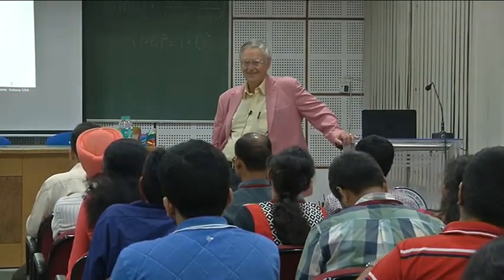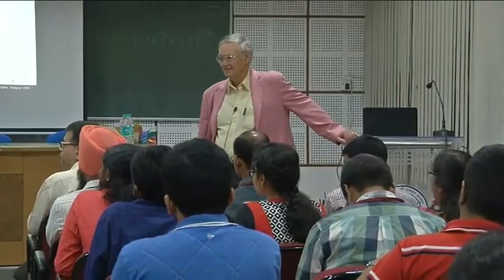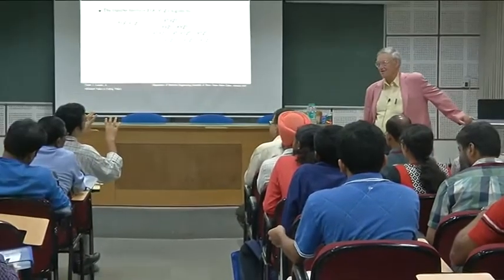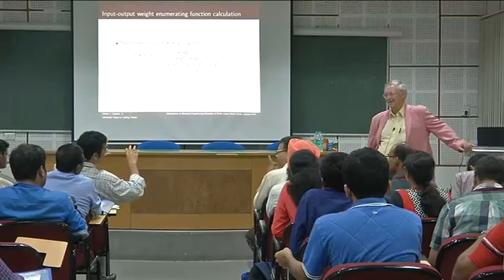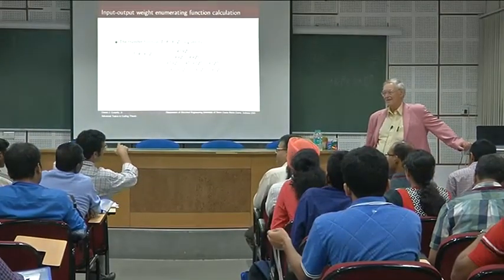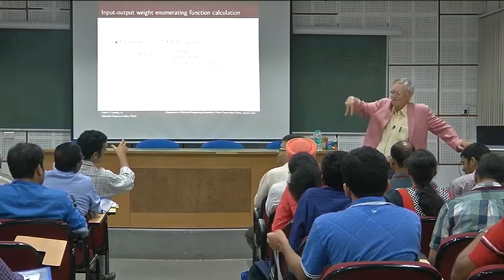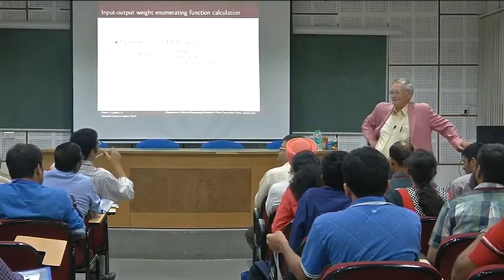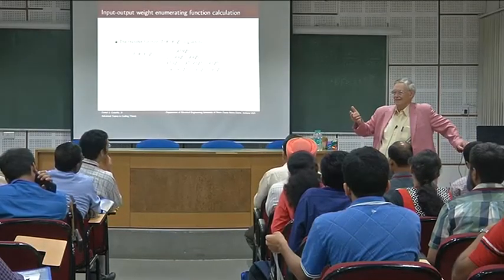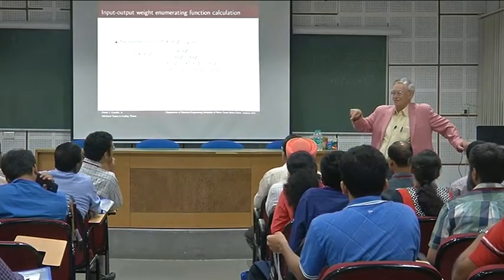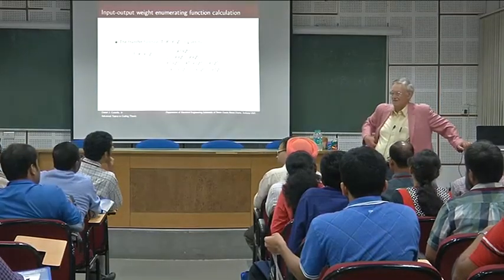Is the controller canonical form related to the concept of controllability in system theory? Yeah, sure. You can control the state. That's because the inputs feed into the shift register. You can't control the states if the inputs don't feed into the shift register, but if they do, then you can drive the states with the next set of inputs.